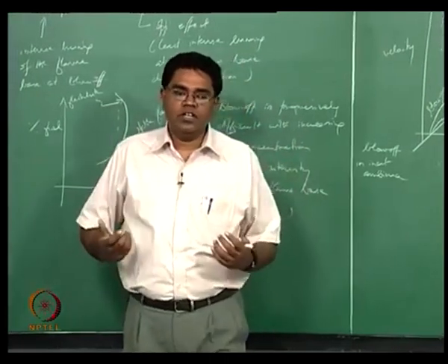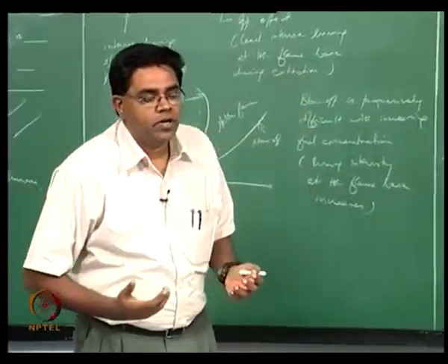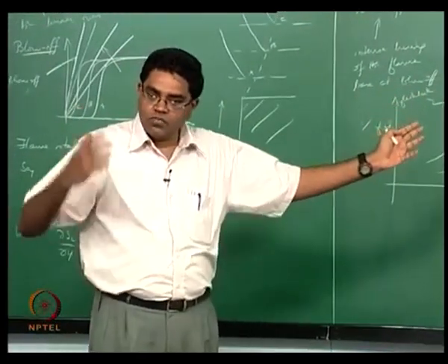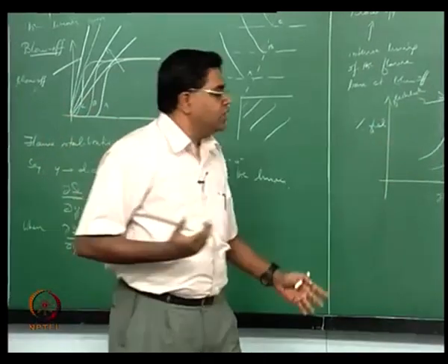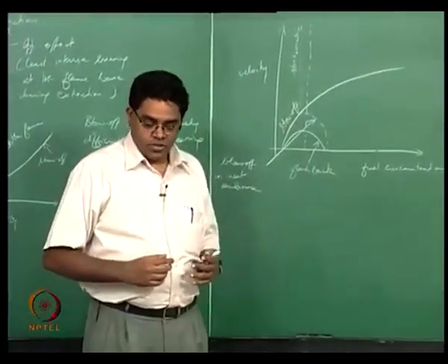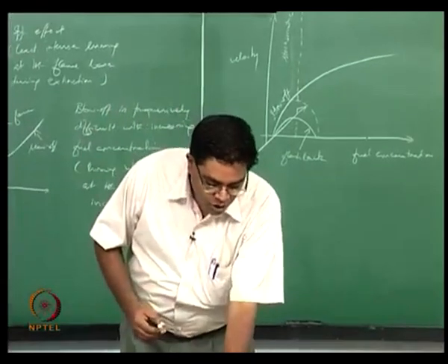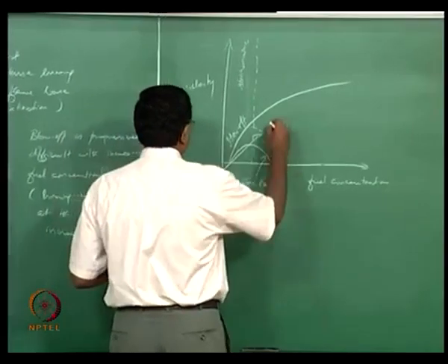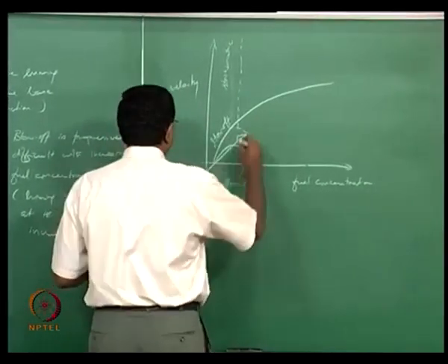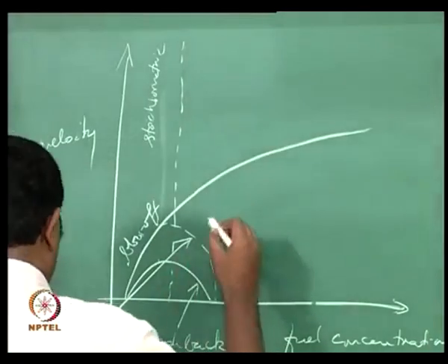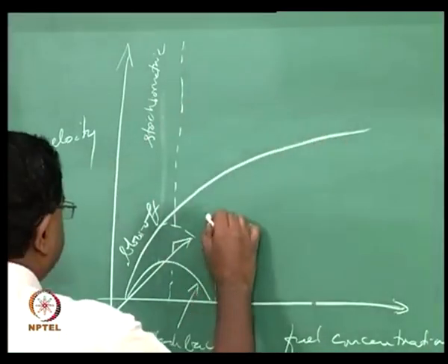Therefore the stability seems to be significantly protected for us in the case of fuel rich flames. That's what essentially is happening, right. However, there is another interesting thing that begins to happen, which is you now have to worry about something called a lifted flame. So somewhere in here you now have another envelope that is coming up in the stability diagram,